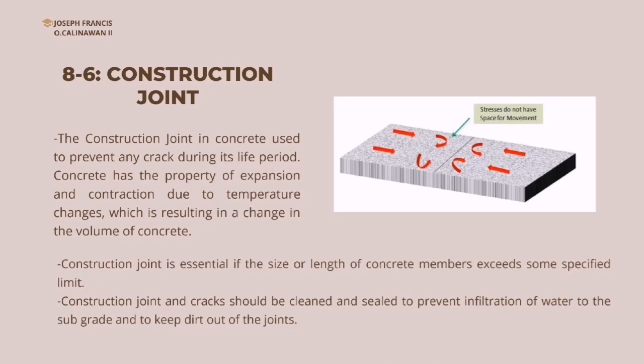Construction joint is essential if the size or length of concrete members exceeds some specified limit. Construction joints or cracks should be cleaned and sealed to prevent infiltration of water to the subgrade and to keep dirt out of the joints.